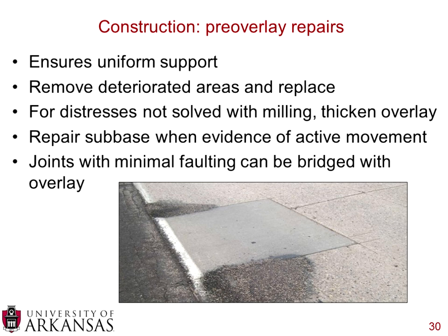And then also something important to point out is that if you have some faulting along your projects, if it's what they call minimum faulting, they didn't quantify that, but if it's minimum faulting, you can simply bridge it with an overlay, so you don't need to go in and diamond grind that off.